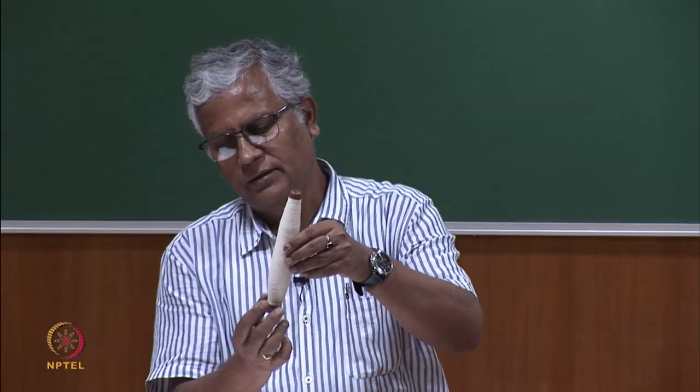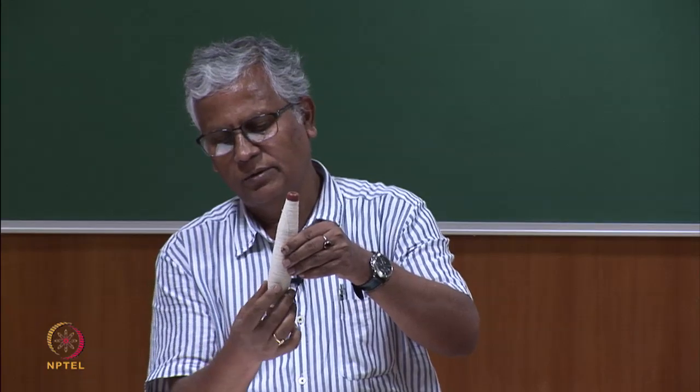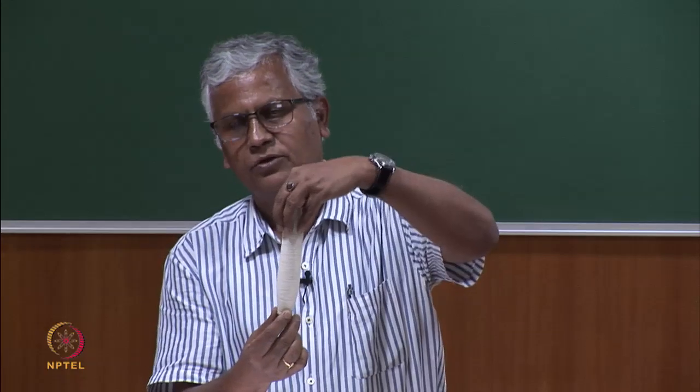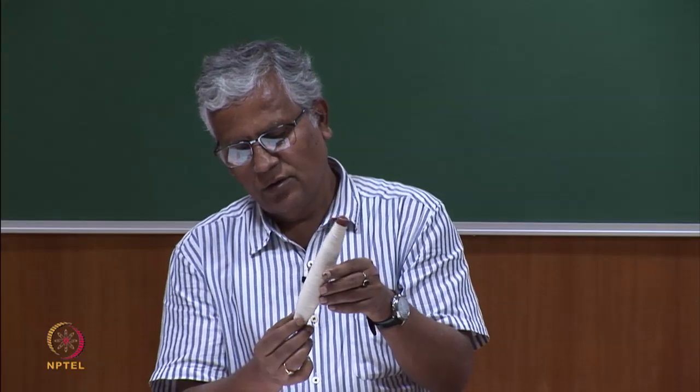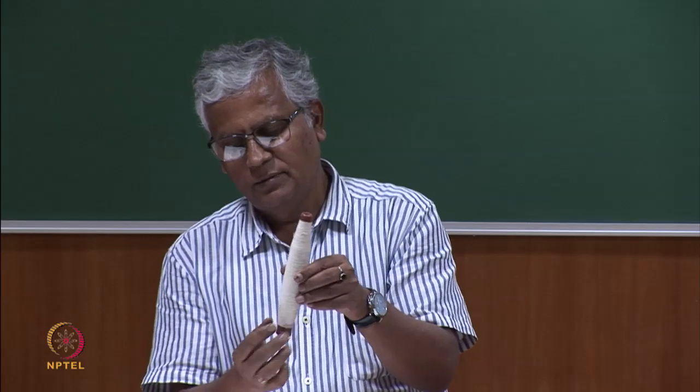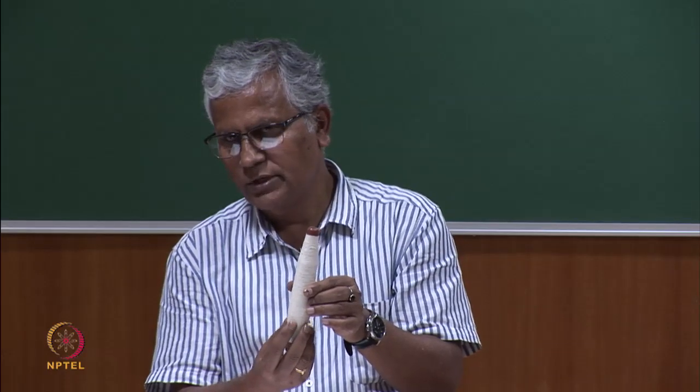In some cases we will find generally the bottom part is a little shorter, the tapered part of the bottom region is a little shorter in comparison to the top region, and in some bobbin building the bottom part is going to be a little curved in nature, which is not really visible here, but in some of the modern ring spinning machines you will find that the base part of the bobbin is not so much tapered, but a little curved. This is the typical geometry of the bobbin.